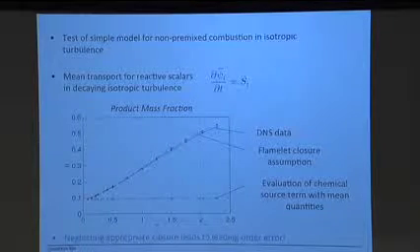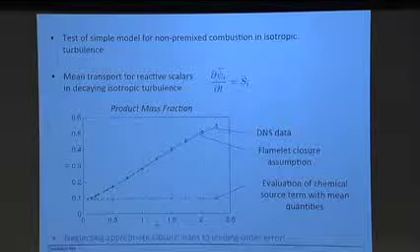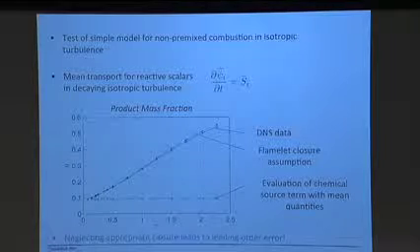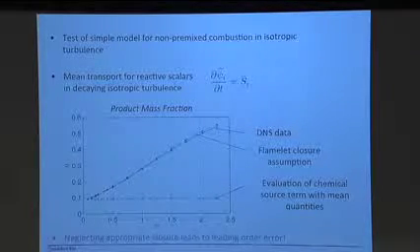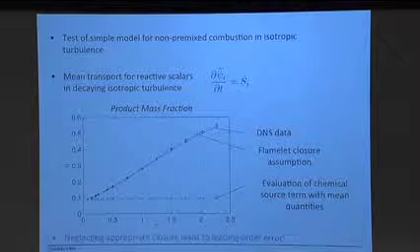Now, as I said, in the beginning the temperature is relatively low, and while fuel and air mix and react, the overall temperature in the box becomes larger and larger. Now, what if I say this here is a chemical source term? So it is basically fuel times oxygen times exponential minus E over RT. Now the average of this, introducing this Reynolds decomposition, gives me a lot of very complicated correlation terms.